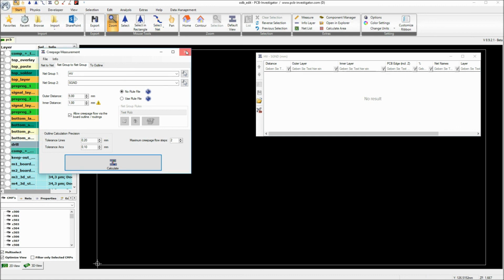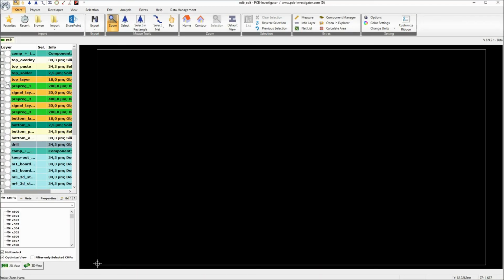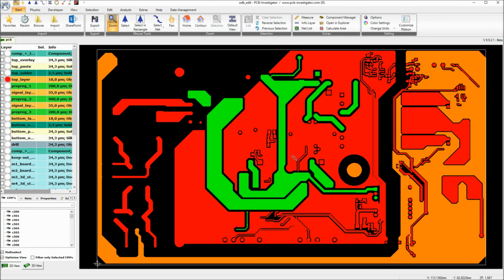Okay, so we are now at the end of this video tutorial. Hopefully it helped you to see what is possible with highlighting nets, measuring between nets, defining net groups, defining colors, getting the length of nets, finding nets according to the net list or starting from a component, and also how the creepage analysis works, and that it is a very, very mighty tool and simulates the creepage also going through routings and going through the PCB edge.